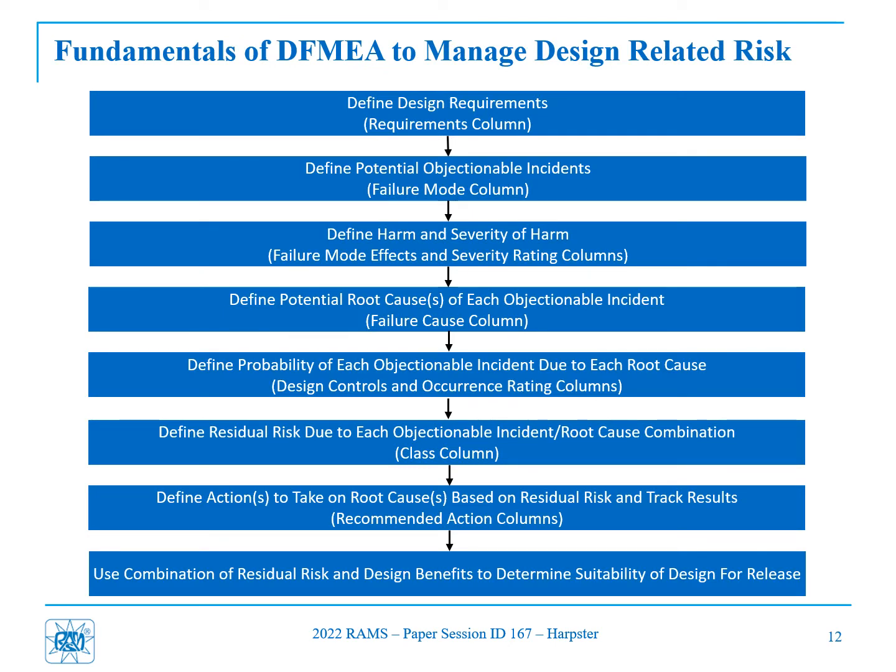Let's now look at the fundamentals of performing a design FMEA to reduce design-related risk. One of the common misunderstandings of design FMEAs, because of the name Design Failure Mode Effect Analysis, is that the purpose of the design FMEA is to determine all of the possible failure modes and then to try to mitigate the effects of those failures. That is not the purpose of a design FMEA.